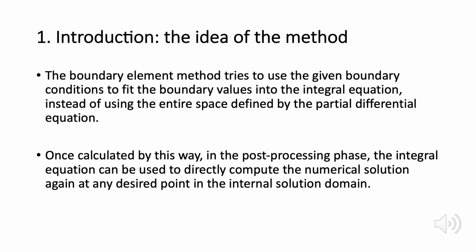The idea of the method. The boundary element method tries to use the given boundary conditions to fit the boundary values into the integral equation, instead of using the entire space defined by the partial differential equation. Once calculated this way, in the post-processing phase, the integral equation can be used to directly compute the numerical solution again at any desired point in the internal solution domain.